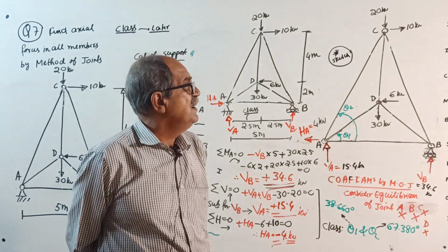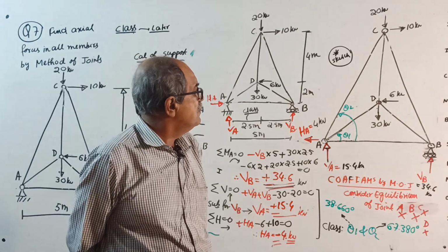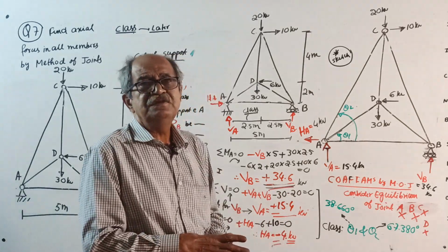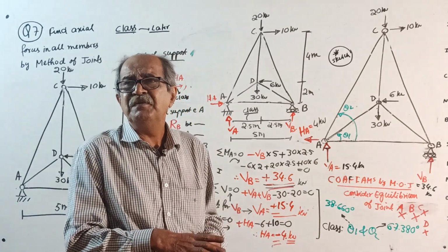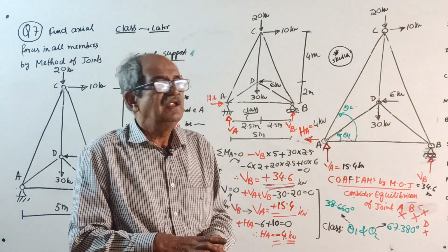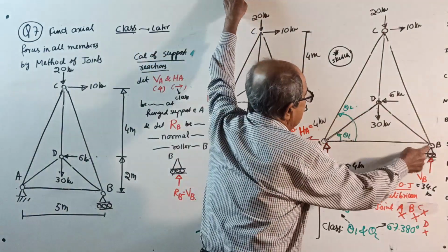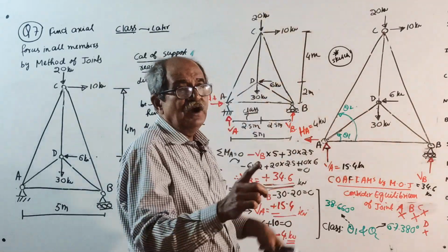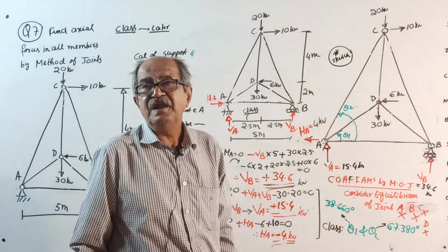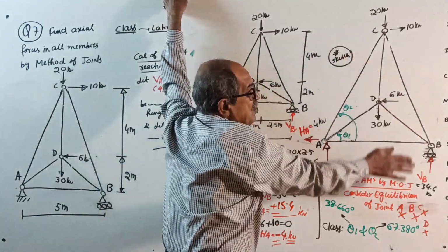Then, when it is found that it cannot be solved, doubts came. Why can it not be solved? It is a perfect frame. Only triangles are there. Only triangles means it's a perfect frame. Why the problem? There is a reason. Even if only triangles are there, this is not a perfect frame. This is a redundant frame. So I have to rub the full board and write.